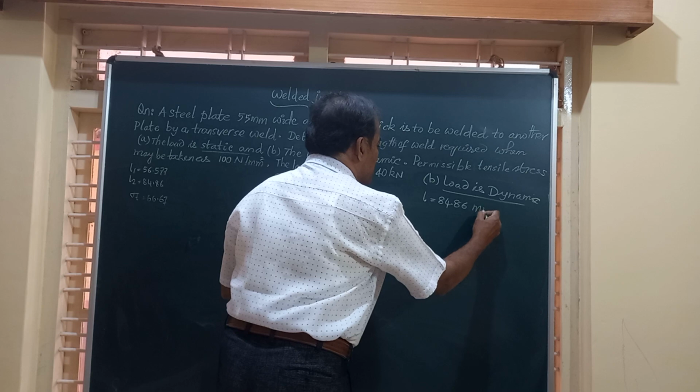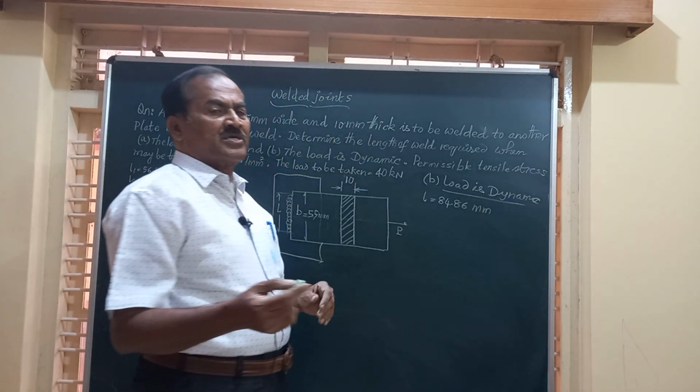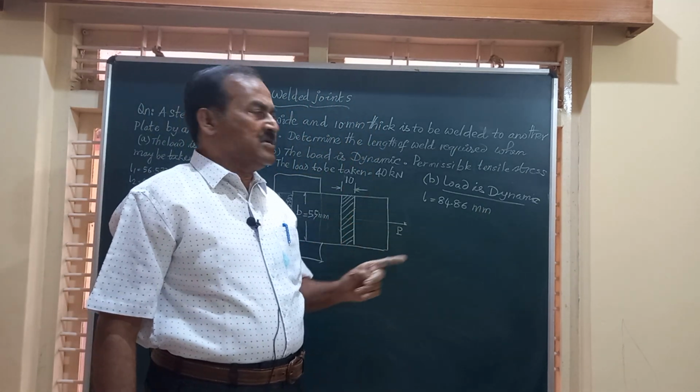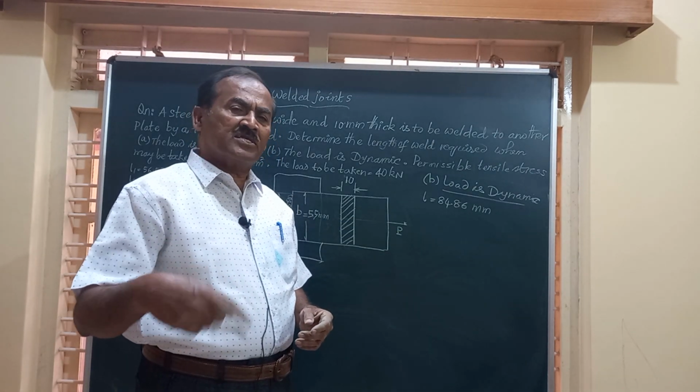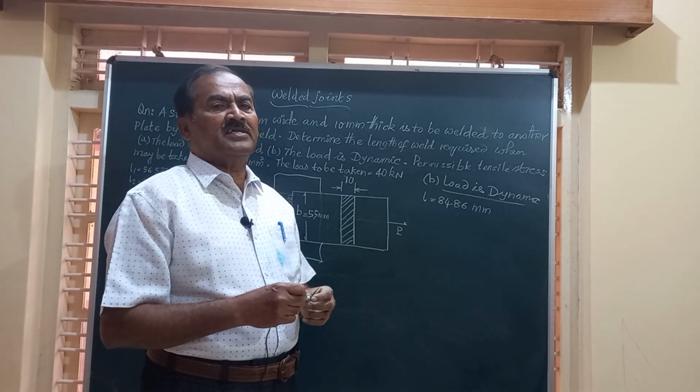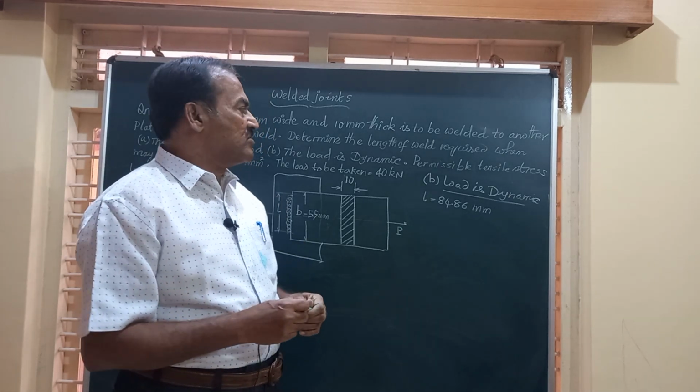We get L equal to 84.86 millimeter. Friends, if you observe case 2 with case 1, the length of welding required here very obviously is higher than that obtained in case 1, that is for the static load.